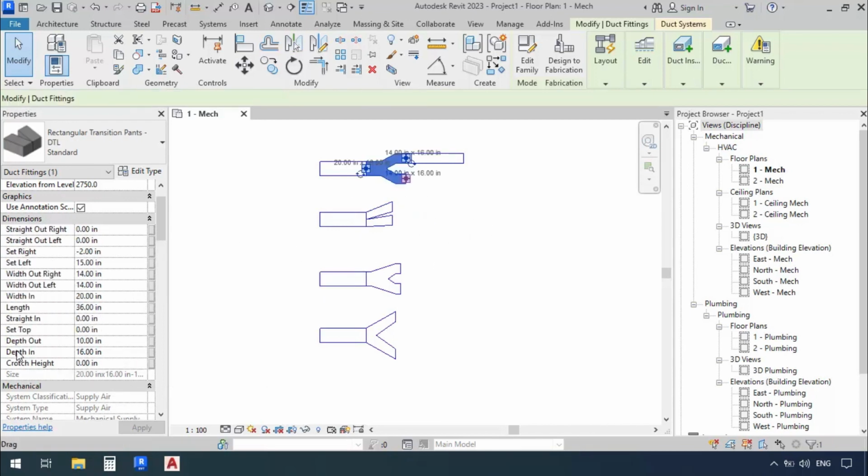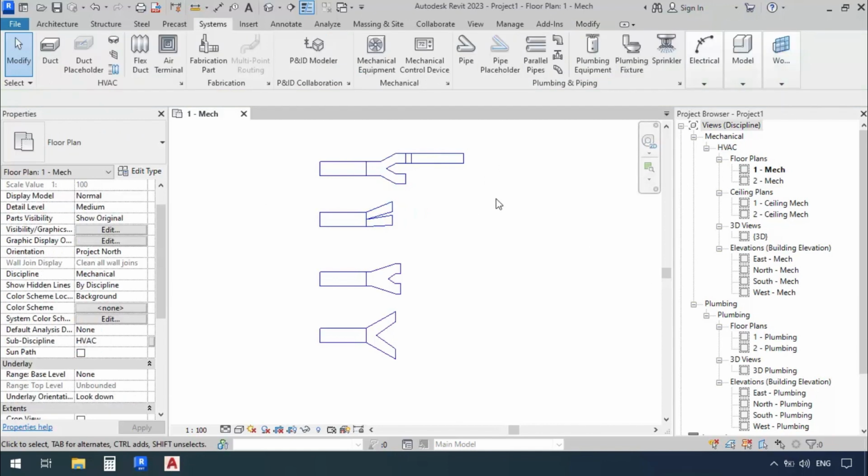But as for the other fittings, we can only change their dimensions. So considering what function each of them serves, the plan that you have, and the dimensions that you are given, you can find and select the proper fittings from the Wye's or the Pants and V's folders. Then you can load them, then completely coordinate them with your plan by changing the sizes.